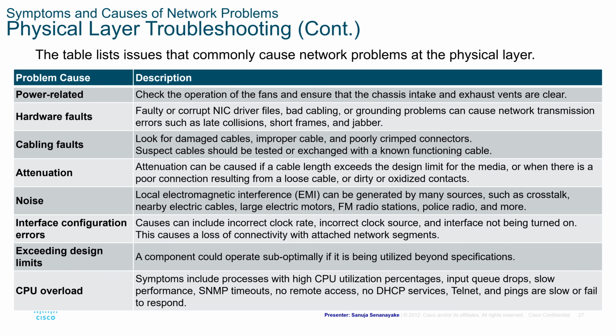And when it comes to electromagnetic interference, it is never recommended to put network infrastructure cables along with electrical cables. So if you have a ceiling with a channel with a lot of electrical cables going, you should have a separate channel for the network infrastructure. You shouldn't put your Cat5e, Cat6 and those types of cables with the electrical cables, because that will most likely create electromagnetic interference. Not so much with the fiber optics, but everything else, yeah, you need to make sure that you separate those ones.